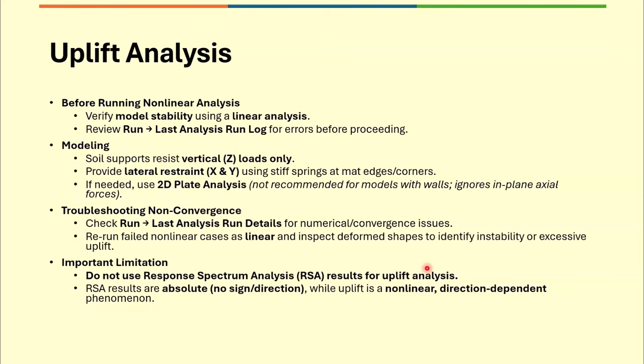Or you can also run this using the 2D plate analysis, but it should be noted that when 2D plate analysis is enabled, it ignores in-plane forces. If that is significant, you should use full 3D analysis, providing lateral springs as restraints for the lateral directions.